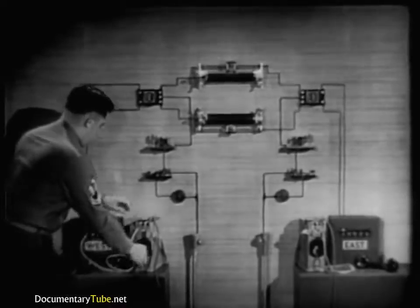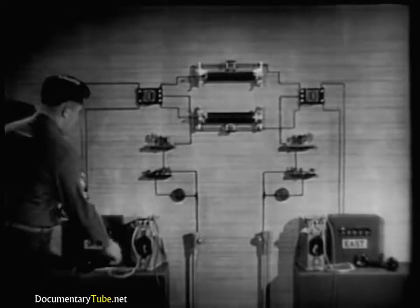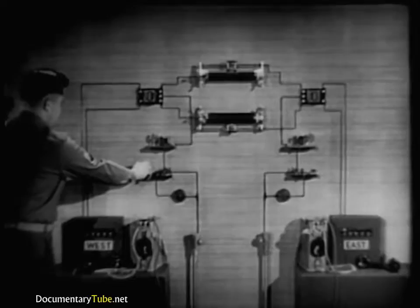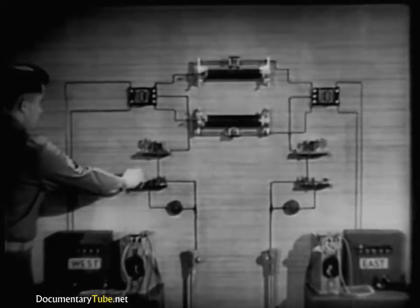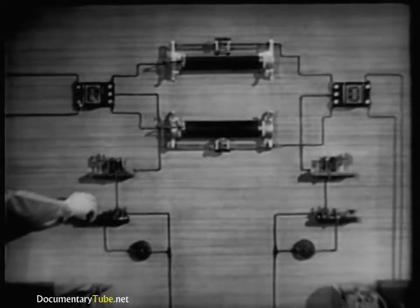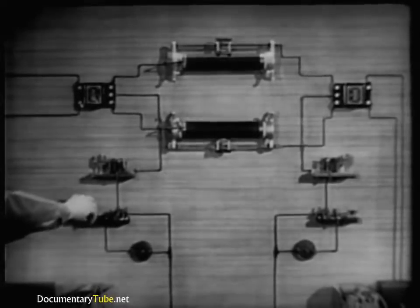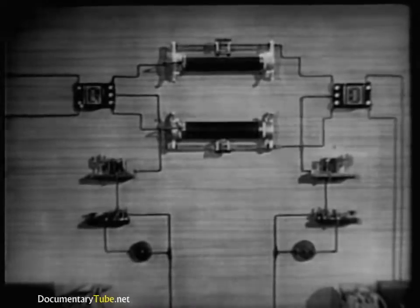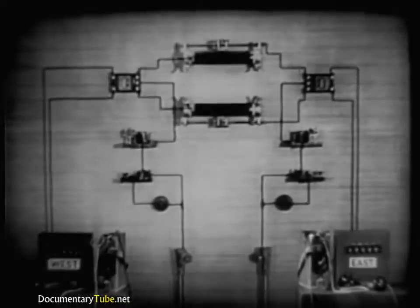The newly installed telegraph circuit can operate without interfering with the original telephone circuit. This new channel is a simplex circuit that may be used for either telephone or telegraph. It is rarely used for telephone, however, because like all ground return circuits, it is apt to be noisy.